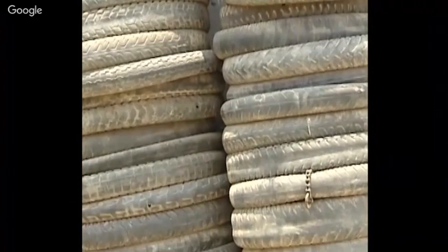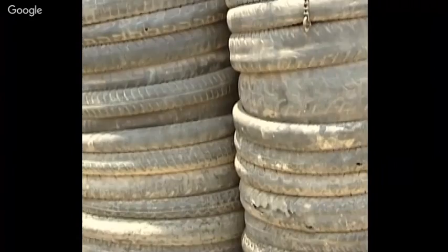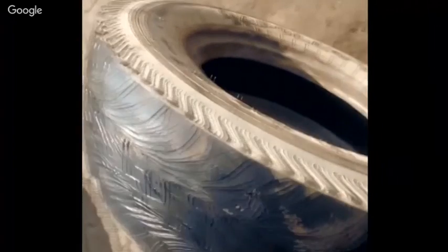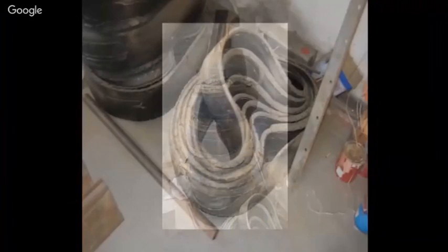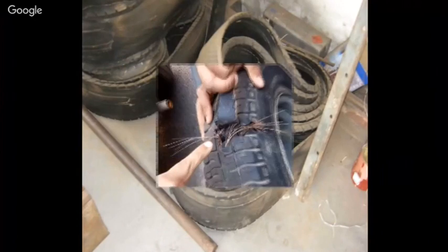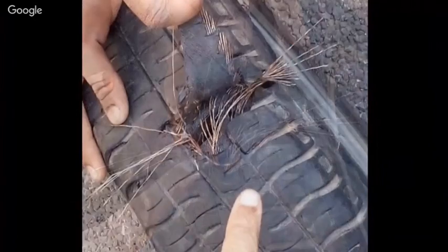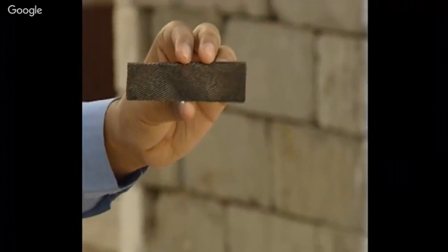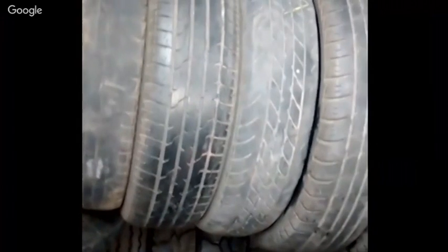The reasons behind using worn-out radial tires are manifold. Primarily, radial tires are made up of a copolymer of styrene butadiene rubber, which is a viscoelastic material. Secondly, the base part of the radial tire, known as ply, has mostly steel wires embedded diagonally in the rubber, which enhances stability, strength, and viscoelastic property of the material. Thirdly, they are available at a very cheap cost in the kabadi market.